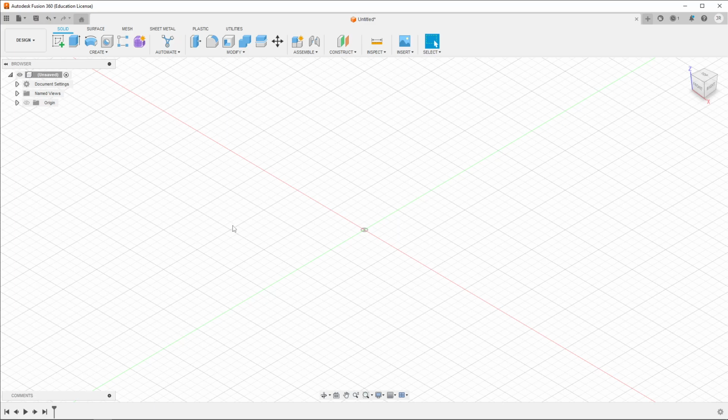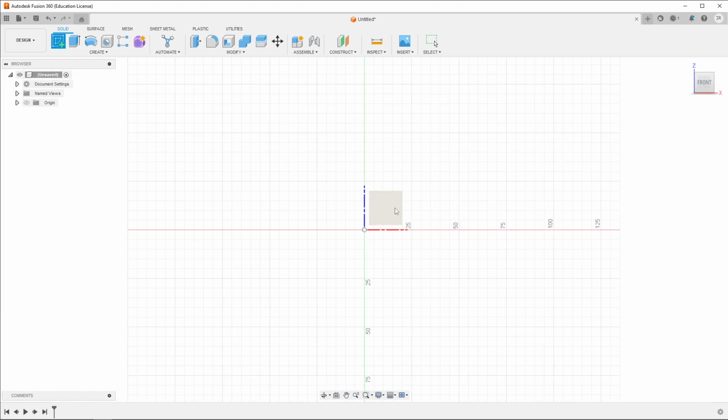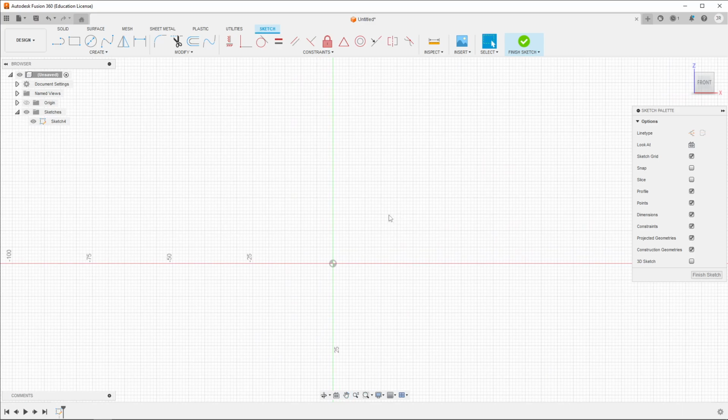So first thing we're going to do is make a sketch, and this is just going to be an arbitrary sketch, just to see the point. I'm going to use a front view, so I'll select the front. I'll use a new sketch. I'll choose this selection, and I'm going to use the origin point as a center point. As long as you have some axis, you can always draw a line, and that's fine, but it's very convenient often to do a line on the axis. So I'll start off by choosing from an origin straight up, and make sure it is vertical.